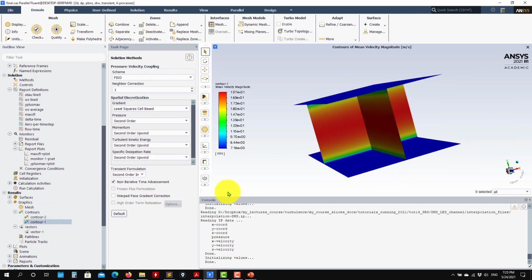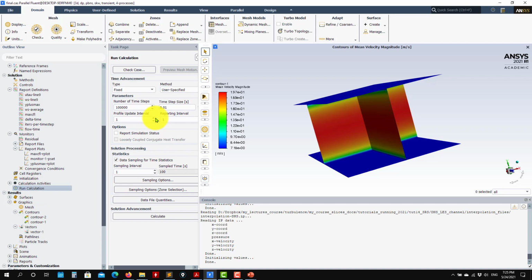So the point here, we're in the URANS, and here in the numerics, be careful that this case we're going to run, but to get also an estimate of this time step. If I launch this simulation, you're going to see the time step. Remember that here now you need to set a monitor for the maximum CFL. The idea is also in this URANS that is very stable, we can play around with time step and get the ideal time step to move to the LES.